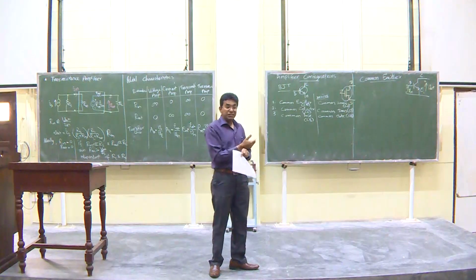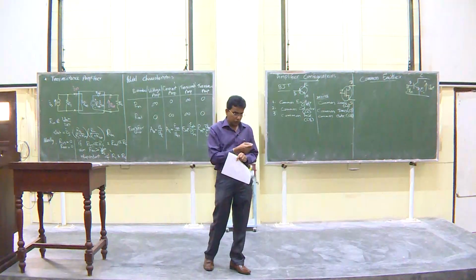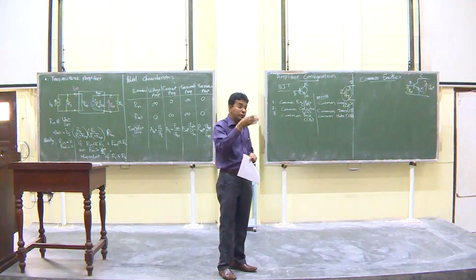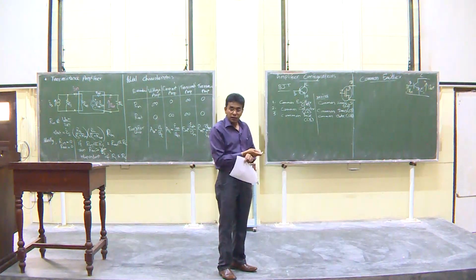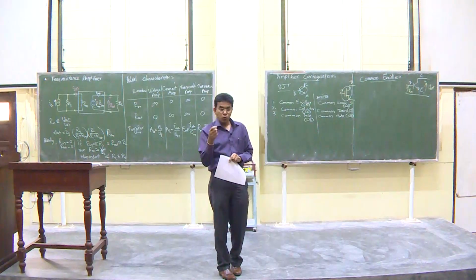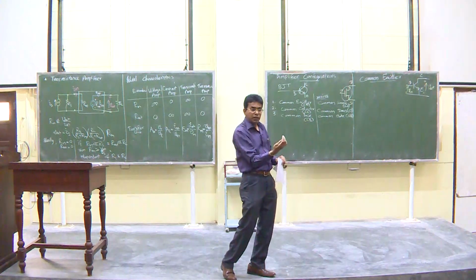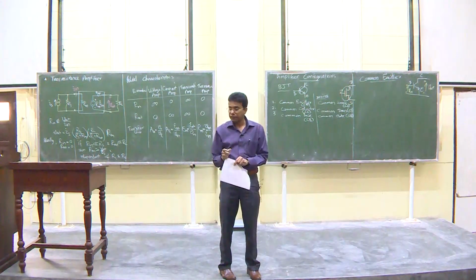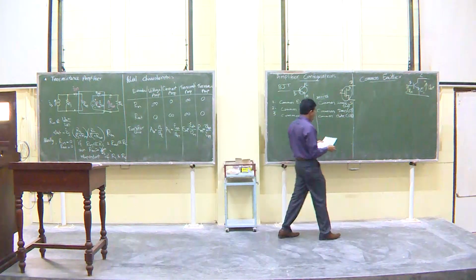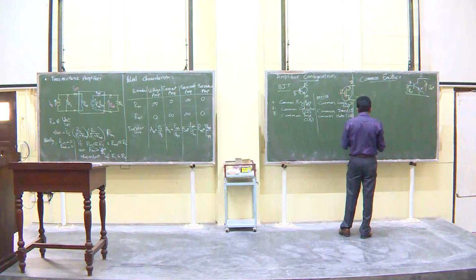Now, even when there is a small resistance to control the AC gain, we still use this terminology, because that small emitter resistance can be considered as the emitter spread resistance, which is already inside the transistor. Later on we will learn a trick which we can use to transfer that resistance in the emitter into the base side, so that the emitter becomes directly connected to the ground. We will learn that later. Okay? So this is the common emitter configuration.